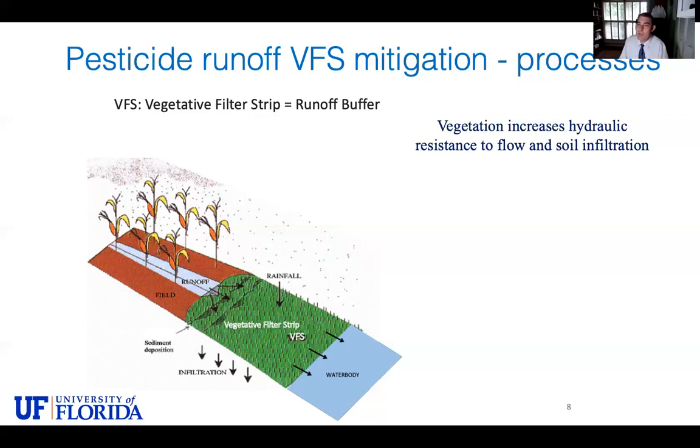Because the roots are breaking the ground, there is organic matter accumulation, and there is soil structure that improves in time. Studies that have done parallel measurements of infiltration in these buffers, once they have been established for a while, and the infiltration in the field, indicate that there is about an order of magnitude, a factor of 10, difference in infiltration characteristics on an established buffer with respect to the field.